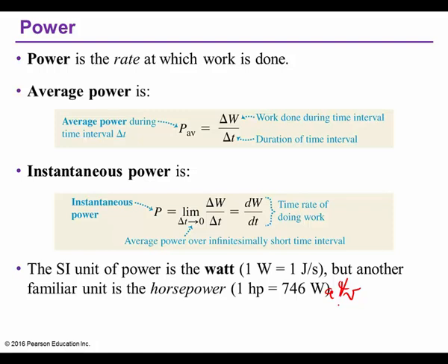My dad, when he worked here on maintenance, they were burning out compressors on the big walk-in cooler at the cafeteria, and they'd burned out like 2 in a year. Well, that's just unheard of. You just don't do that. Dad said, there's not enough voltage. We don't have enough voltage or amperage. So he took his voltmeter, and sure enough, it was like 190, and it was supposed to have been 220 at least.